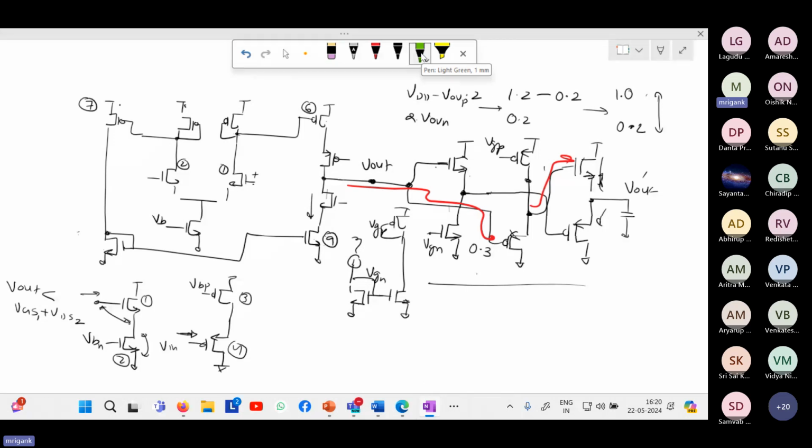And then there are two parallel paths which allow you to handle the entire voltage swing. So once again, for very low voltage, what will happen? Your NMOS will be off, and only the PMOS will be conducting. It will pass the signal here, but it will lead to a VSG shift. But then the NMOS will again lead to a VGS shift downward. So for the PMOS, compared to the gate, the source voltage will be higher by VSG. But when it comes to the gate of the NMOS, it will again pull it down by VGS. Assuming that the VTs are close and the overdrive voltages are small, it will have some kind of cancelling effect.